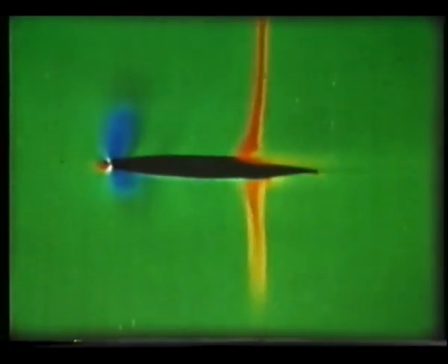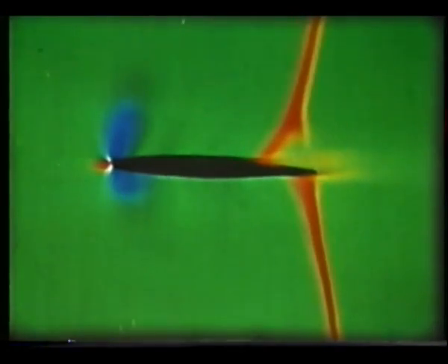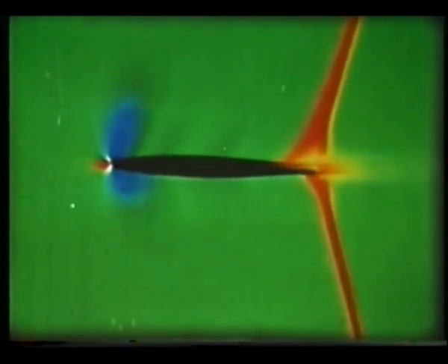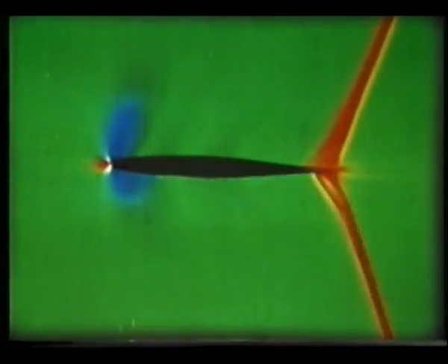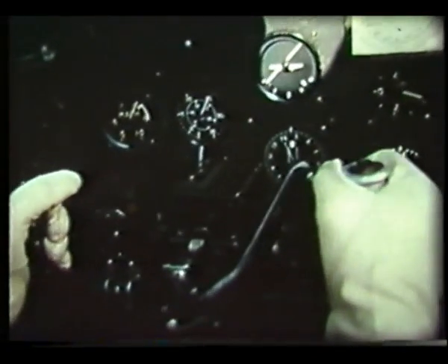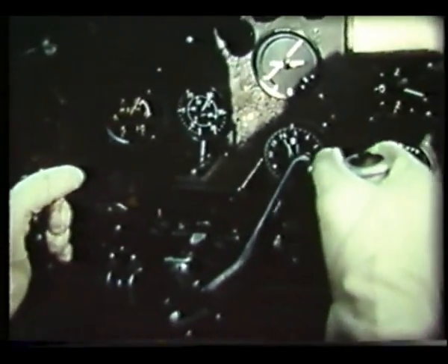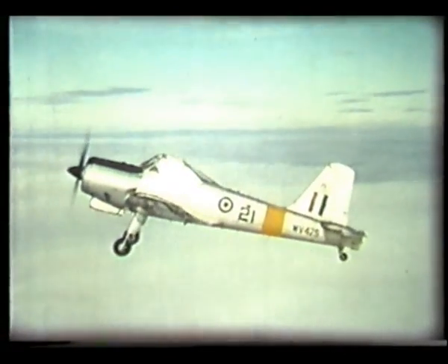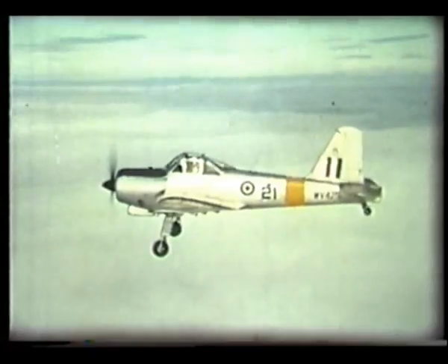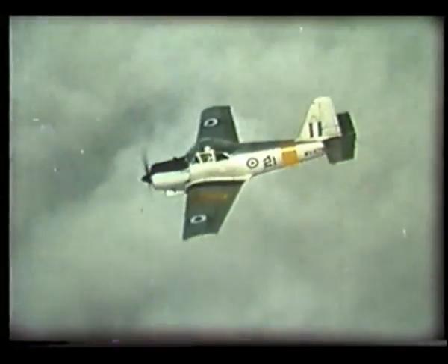But it is flow separation that causes most of the troubles in the earlier part of the transonic range, when the shocks are still moving back. Once the shocks have reached the trailing edge, separation is much less. It is flow separation that causes the shock stall, so called because the effects in flight are rather like the normal low speed or high incidence stall, also caused by separation.